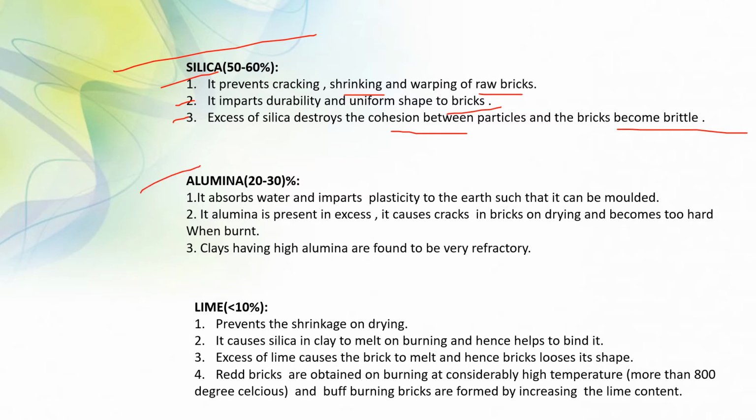Next, alumina, 20 to 30%. Number 1, it absorbs water and imparts plasticity to the earth such that it can be molded. Number 2, if alumina is present in excess, it causes cracks in bricks on drying and becomes too hard when burned. Next, clay having high alumina is found to be very refractory.